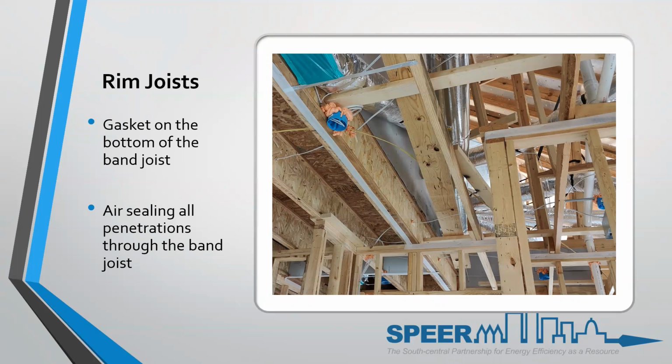Lastly, it's a pet peeve of mine, but in this photo, there are also two framing trash pieces of wood that are left in the attic. This creates gaps and deficiencies in the attic insulation, so they should be removed before attic insulation goes in. Most of the time, it won't be. Why? At this point, it's easy because you can just drop it out of the ceiling, but to remove it after the sheetrock's been installed means carrying that piece of wood all the way to the attic opening and trying to get it out, or cutting it up.